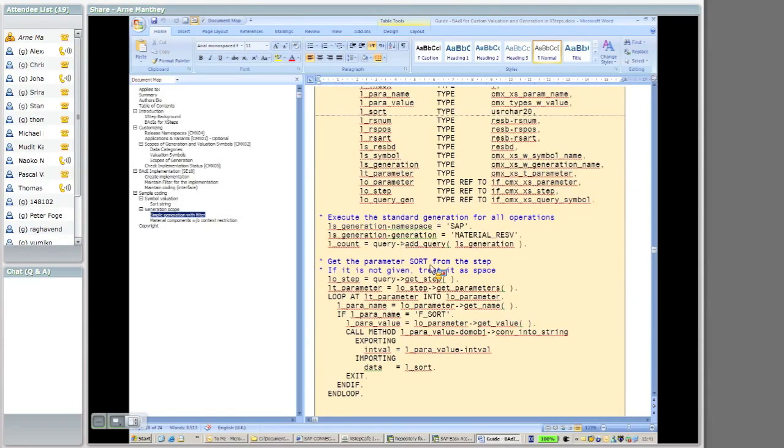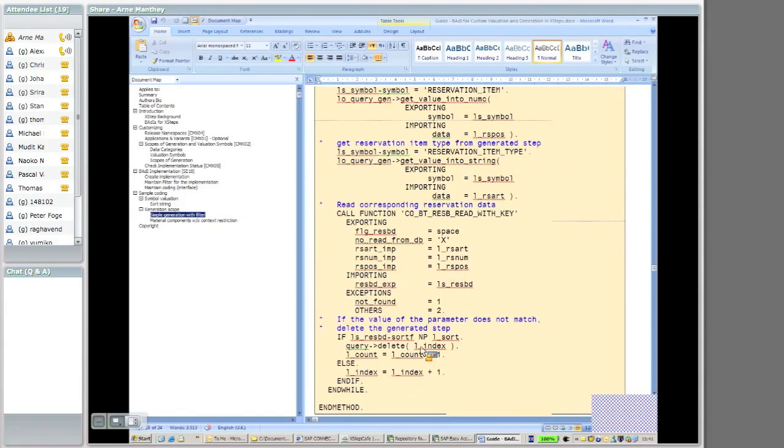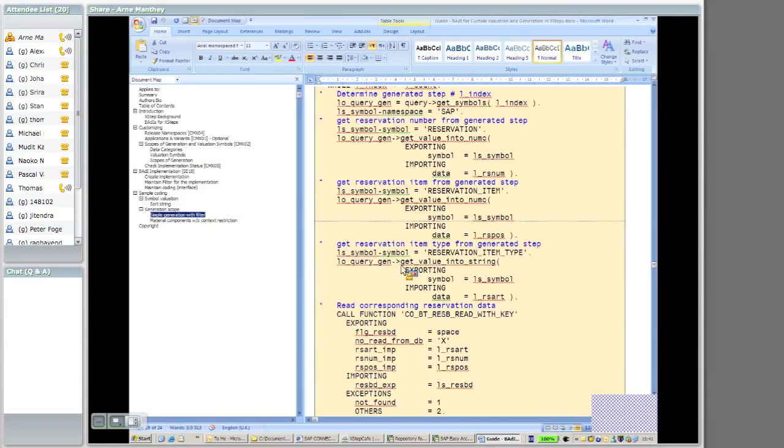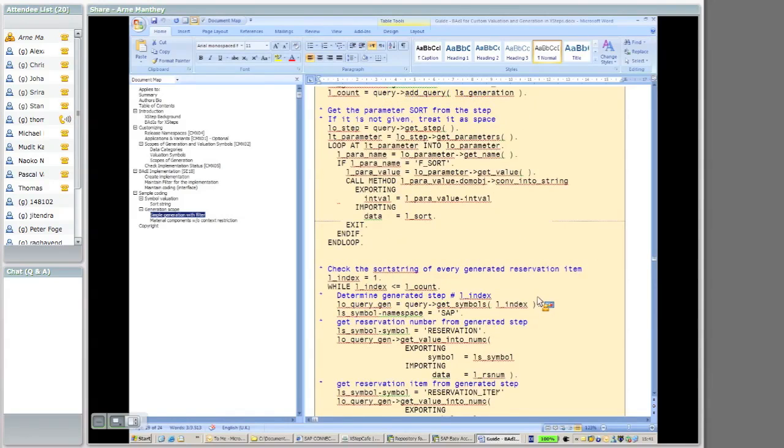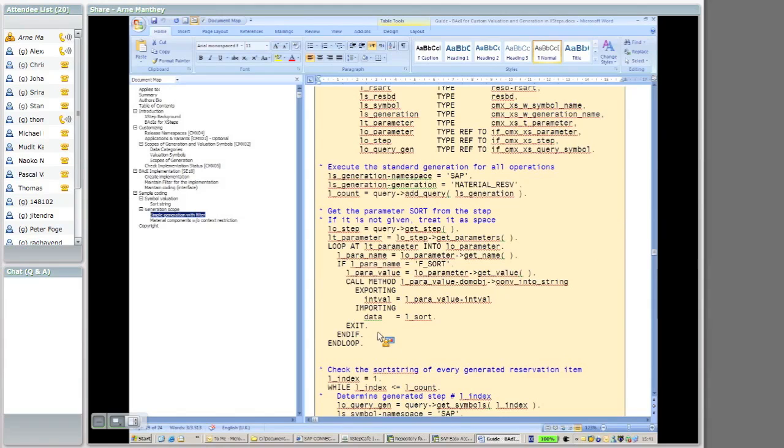Here I'm using a delete method on each line. So I'm querying through every line that is returned here, and then I check whether it matches a certain criteria. Yes, and for example in here I have also included a sort of parameterization on this generation scope. Maybe for those of you who have created the normal process instruction destination, control recipe destinations with the filter that is available there in the material section, there you have a nice filter view where you can select certain filter criteria. This you have to do for each BAdI implementation on your own, but of course it gives you a lot of flexibility.